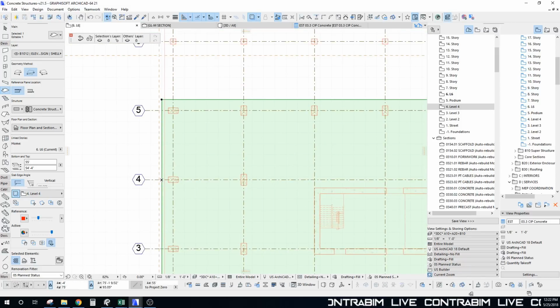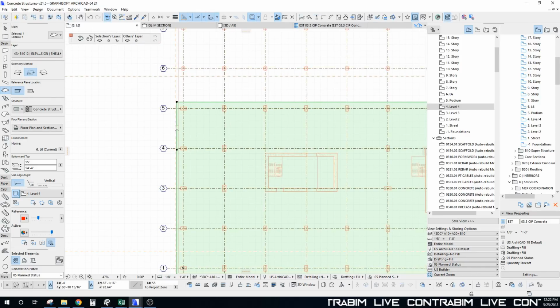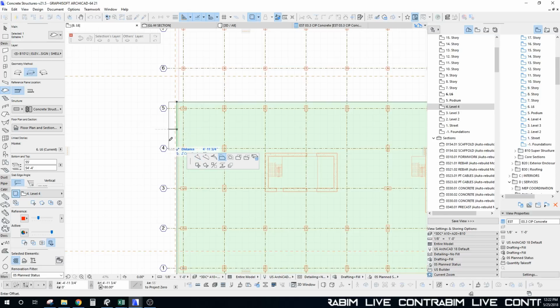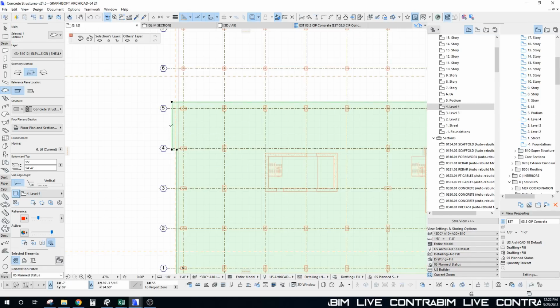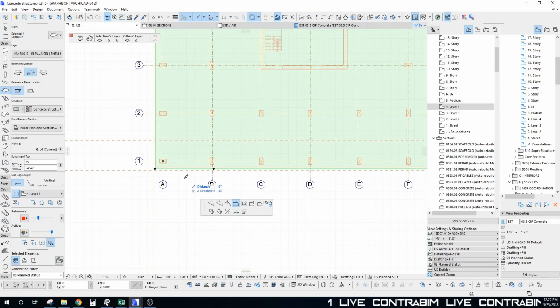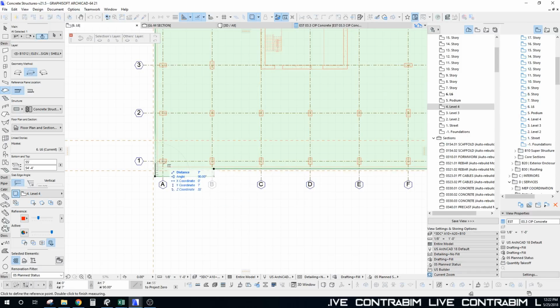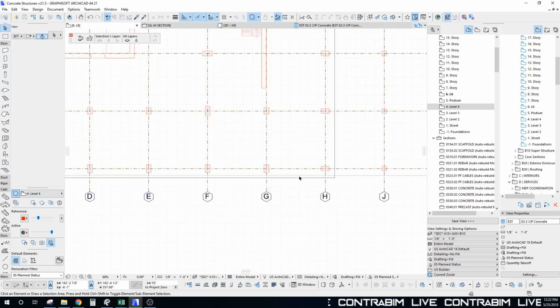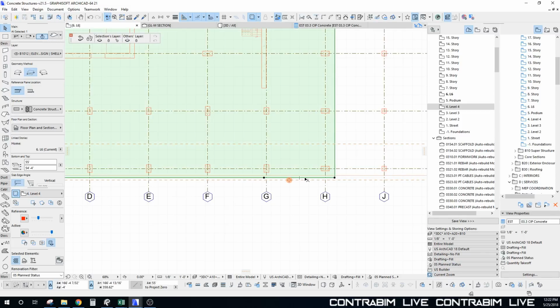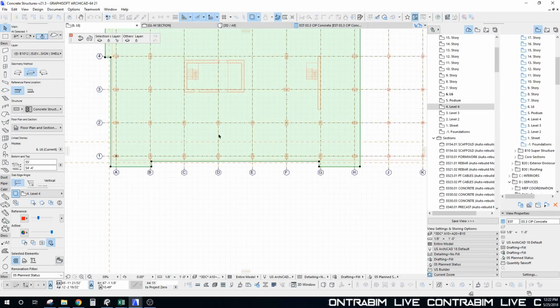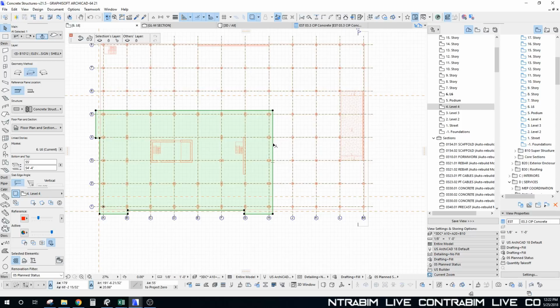Can add one there. And so we can push some of these just out, just 3 feet. One more foot just to get a little bit more definition as we're going up here. So from the column out, you can cantilever 6-7 feet, no problem. So we'll pull that out, and we're just going to do this for each of the different sides.